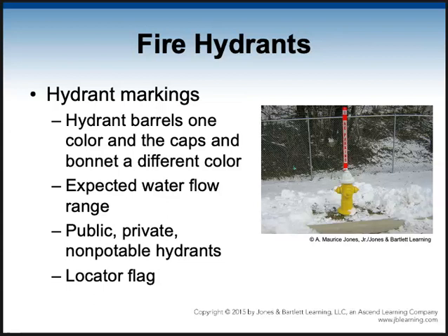Some communities will use different colors for different amounts of pressure on the bonnet or top part of the hydrant. Sometimes in communities like LA County, they want you to put a red head on the bonnet of a yellow hydrant if it's really high pressure.